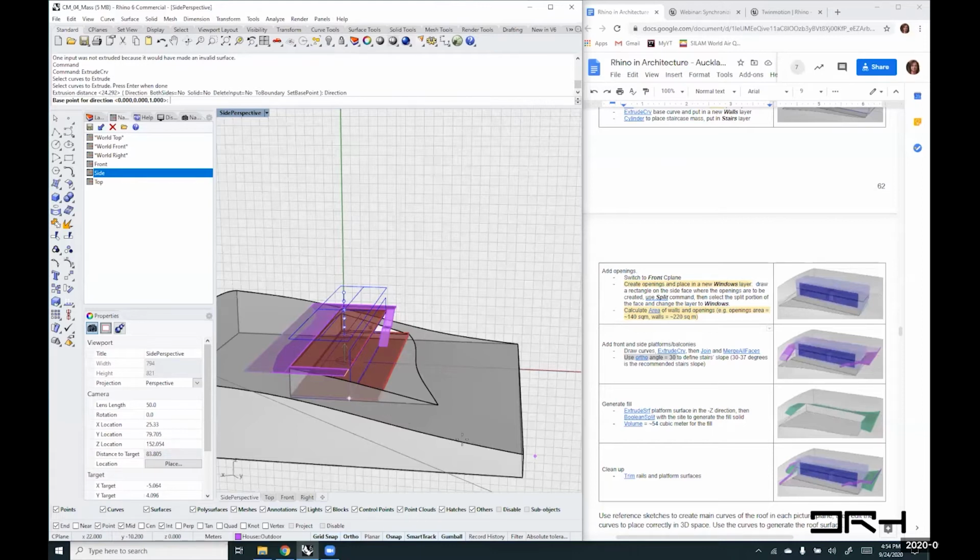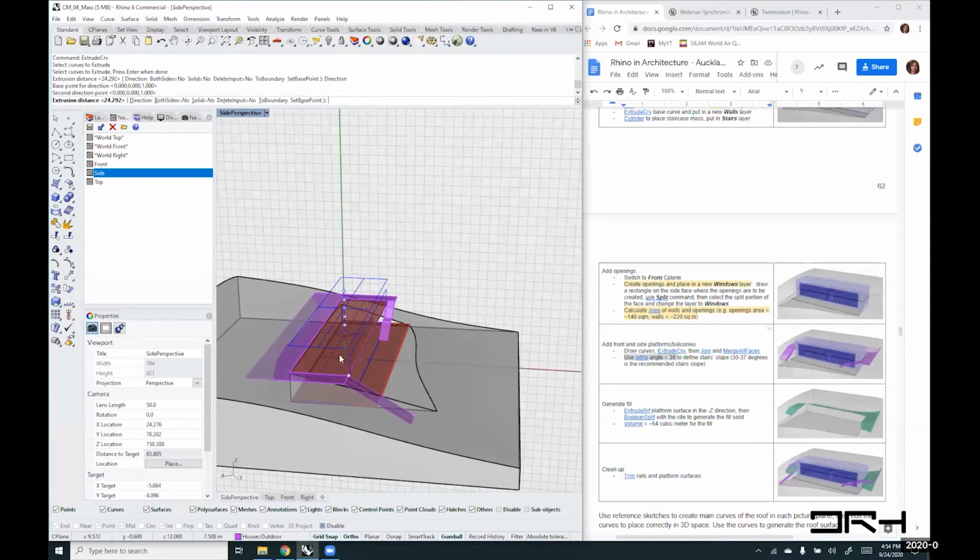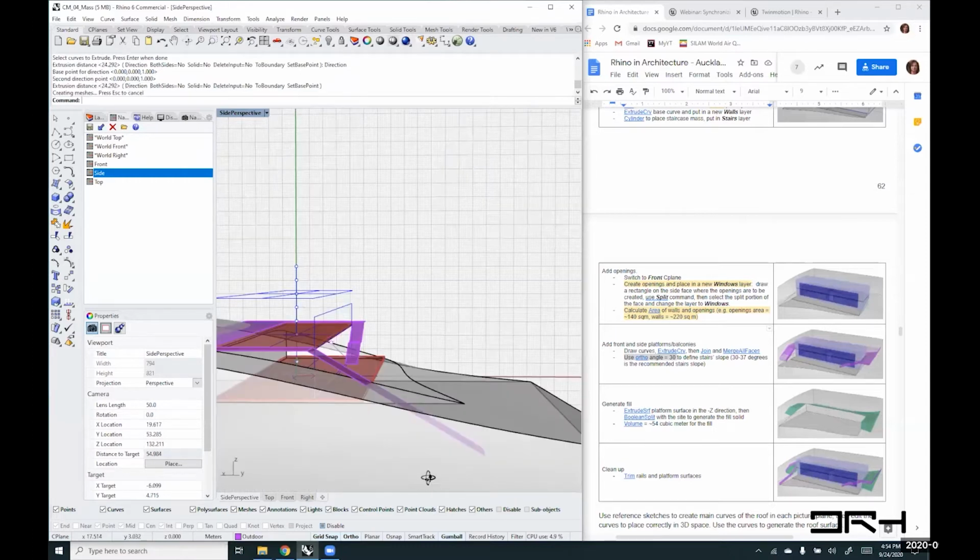First point, second point, and now basically you can extrude it in the 30-degree direction. I was snapping to different geometry, and this is why the extrusion direction was going out of sync with what I want.